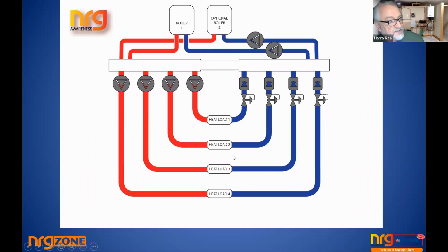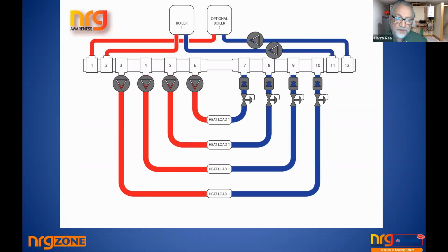So again, that's where the balancing comes in, and it's critical to know the flow rate through the boiler, inasmuch as it's critical to know the common number, or the accumulated number from all of the different zones operating. The reason I showed this, and the only difference with this sketch and the other one, is that again I'm showing the T's, but remember, if this was a 70 kilowatt load, these would have to be 2-inch T's, and the bypass would have to be able to accommodate enough water for the water to flow around, so that you have no resistance. And again, it's just to show that you have all of these T's that have to be put together in a proper way to make sure that your system is right.